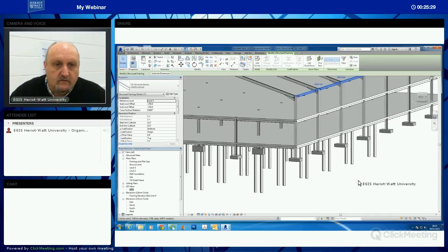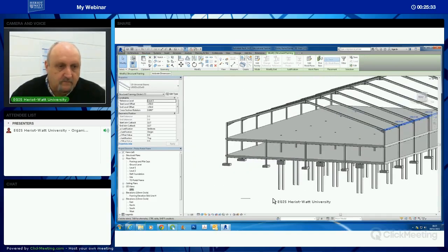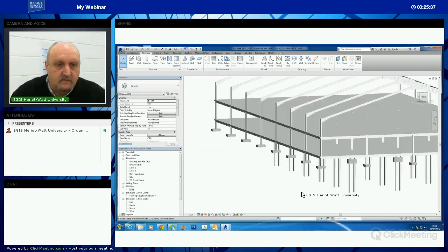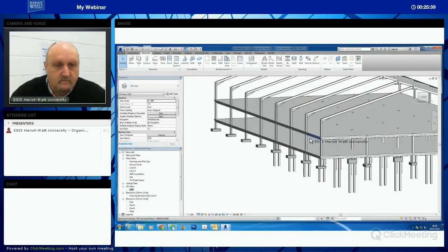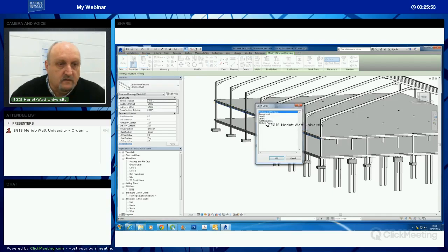And it's fine, they're all in there, they've all got the offset minus 250, that's fine, happy with that. And do the same on this side here. You have to be quite careful when you're selecting. The model gets quite busy. Holding the control key down, that's them all selected. Copy this lot onto the clipboard and paste aligned up to level 2 on this side.